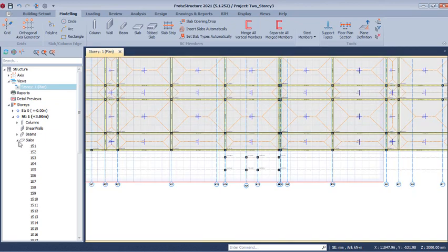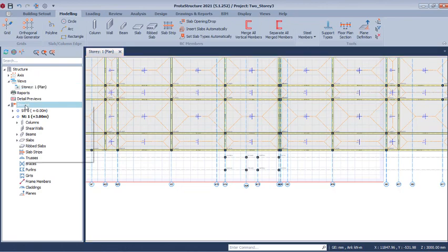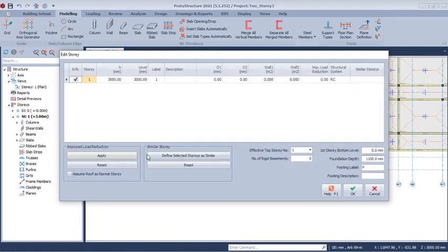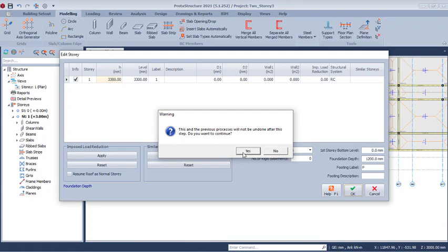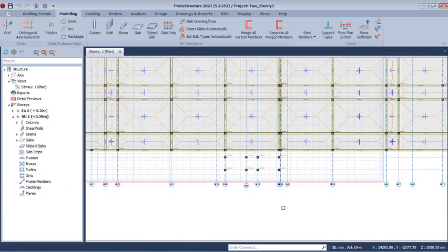At this plan view now, what you need to do is first of all set our story height. For us to do that, select the stories, right click and then click on edit story. In this edit story, you can see the default story used to be 3 meters. So we can go by that. Then for the foundation, since it's a 2-story building, we can just take it to be 1200 right there. So we'll go by this story height, which is 3 meters. But since it is a school, we can make it 3.3 right there. So this is 3.3. After having done that successfully, you click on the OK option. So we have set the story heights right there. So we make progress.